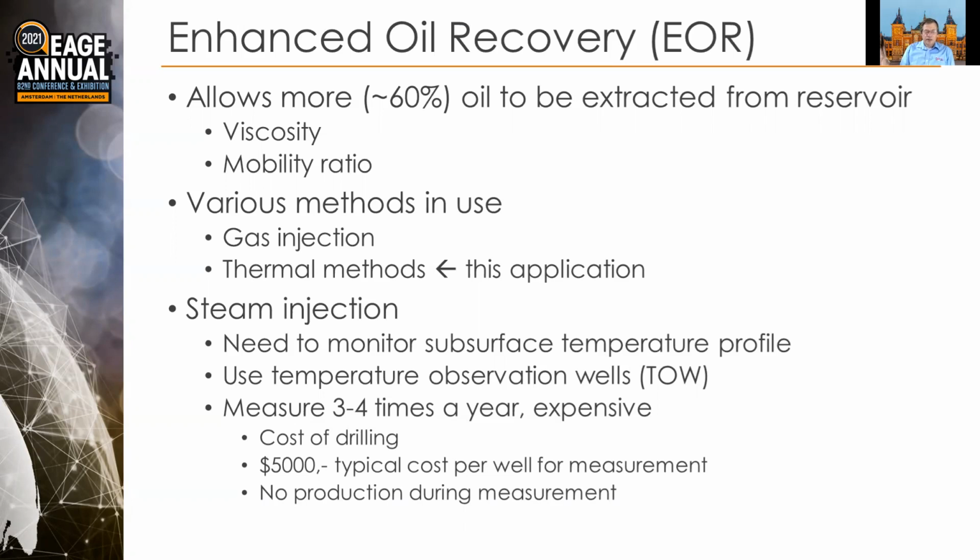We have to make sure the temperatures that are generated by the steam injection are correct, and they are at the right location. There's no leakage, and we're not heating up something we don't want, causing collapse and possible accidents at various places. So we have to know what the actual temperature is in this whole process. The common method of doing this is to use temperature observation wells, which I'll abbreviate by TOWs in this talk. It involves drilling a hole and sticking a thermometer in there and lowering it and taking your temperature measurements. Very straightforward, but it's expensive.